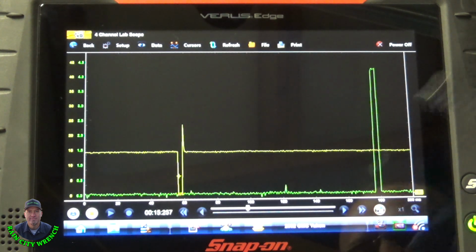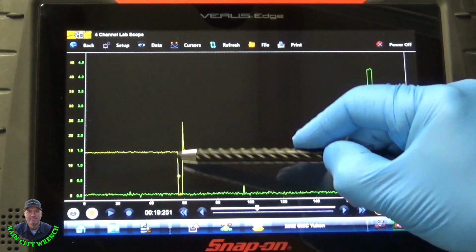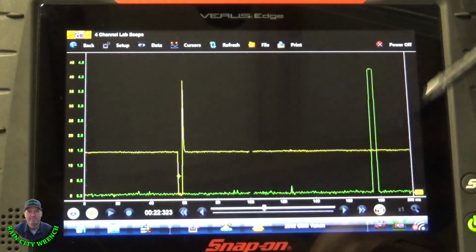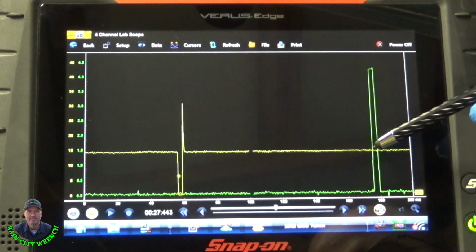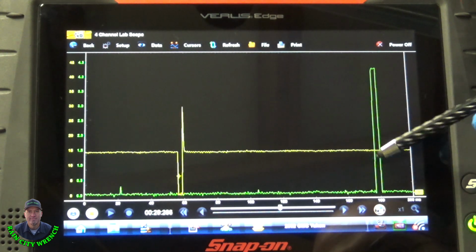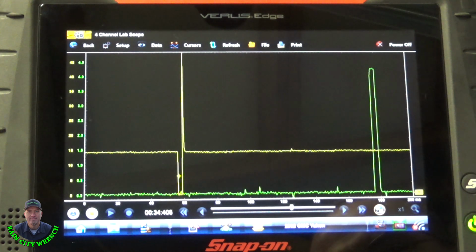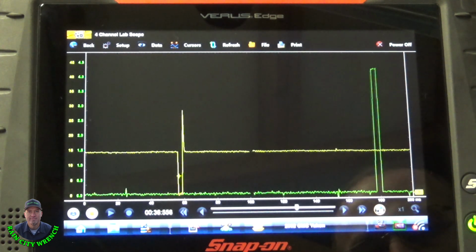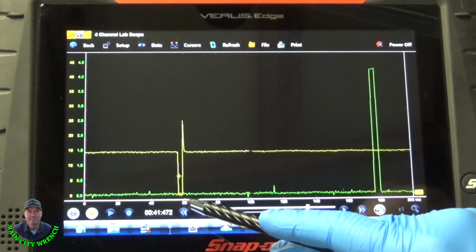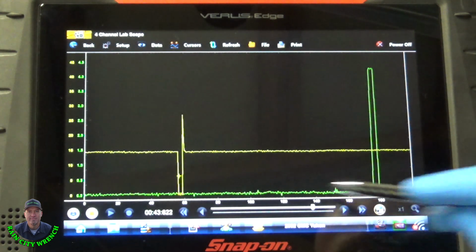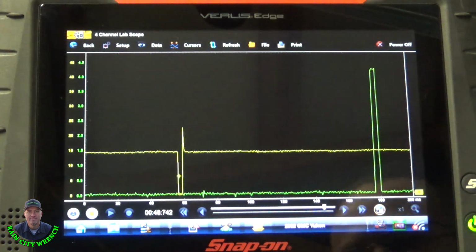These are both on cylinder 1. So it's spraying fuel in here. Obviously this is the intake stroke, spraying fuel, and then this would be compression, top dead center or just a little bit before, and then that's going to spark and create your power event, your combustion event. That happens, you know, within, looks like 140 milliseconds, both of them. 500 milliseconds is a half of a second.